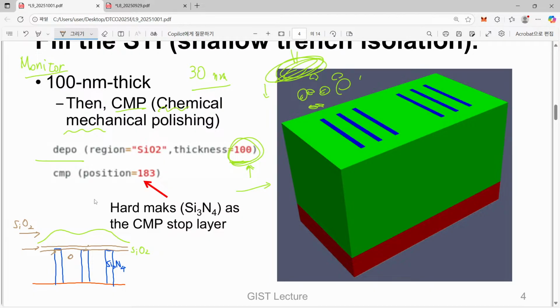Then our monitoring system really recognizes that, oh, there is something resisting against our front movement. Then we say that, oh, that corresponds to this silicon nitride. Material changes can be quite sensitively detected by this CMP process. So that's the reason why, once we have this, it is used as a stopping signal. Oh, please stop. Now we have already touched this hard mask layer.